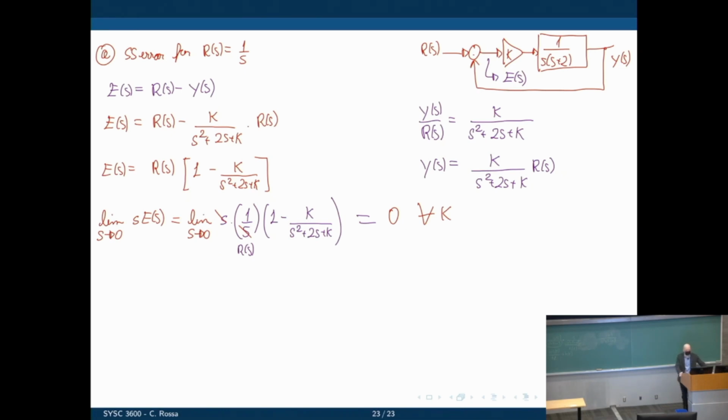So the steady state error is 0 for positive values of K, because negative values of K would result in unstable poles, so the final value theorem doesn't apply. If the system is unstable, there is no final value. If you apply a step input in that case, it would just go to infinity. The robot would go unstable. You can look for videos on YouTube of unstable robotic arms and see what happens. It's a bit chaotic, and it really happens in practice.